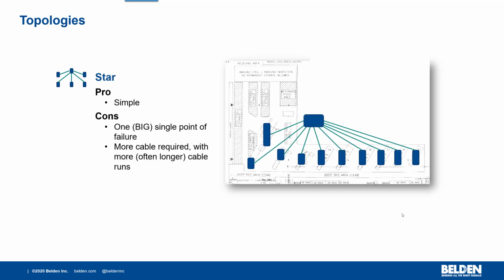The star or hub and spoke topology is something that we see in many plants that have existing networks dating back to the 80s and early 90s. This is largely due to this having been the de facto topology standard for office networks. And as you can tell, this has one glaring vulnerable point of failure, that being the core switch. Other downsides of this topology design are the amount of cabling that is utilized and the associated cost of having to pull additional segments for new networking devices.